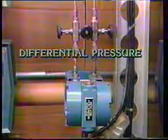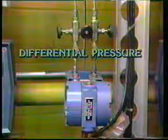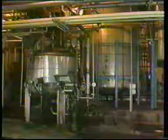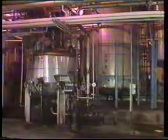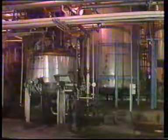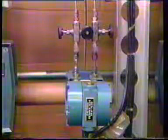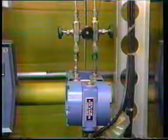Differential pressure is the pressure difference between two related pressures. The key here is related pressures. You may observe a difference in pressure in many places and on many occasions. However, unless they are related pressures, the difference is not differential pressure. We will see how differential pressure can be used to determine fluid flow rate later in this program.